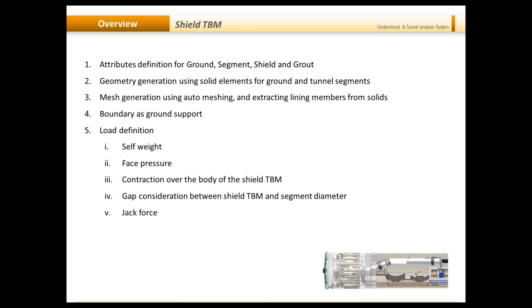Then for boundary conditions, we'll apply just the ground supports, and then we'll define the loads, and this will be the second most popular challenge that you proposed or voted for: how to define and assess these loads. So I'll be talking about surface face pressure, contraction over the body of the shield TBM, gap consideration between the shield TBM and the segment diameter, and the jack forces, because ultimately you are pushing the tunnel boring machine forward.